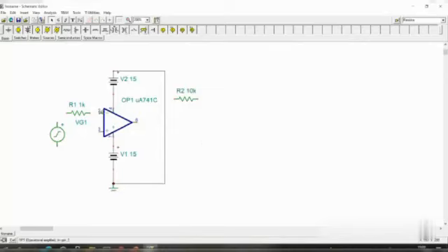So after that, actually I did not connect. So how will you connect it? You have to go and click on this cross mark. Okay, a ribbon like icon will open, so that it will be connected like this. Again here, from here I need to connect to this voltage generator. This is connected, and the negative of the voltage generator should be connected to the ground. Otherwise, it will be floating. So here it is connected.